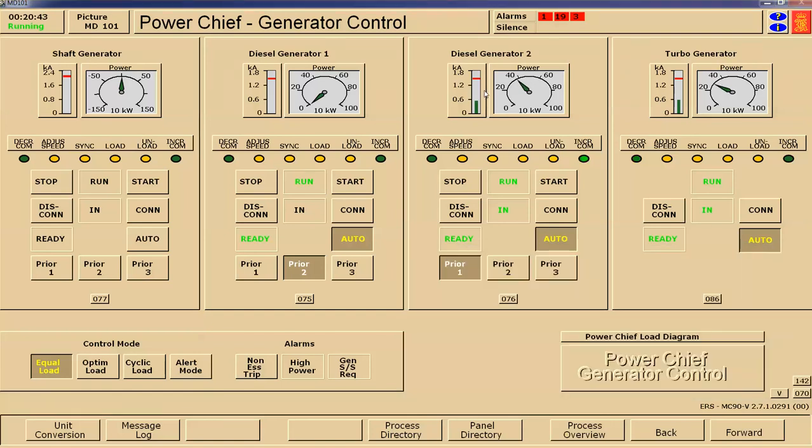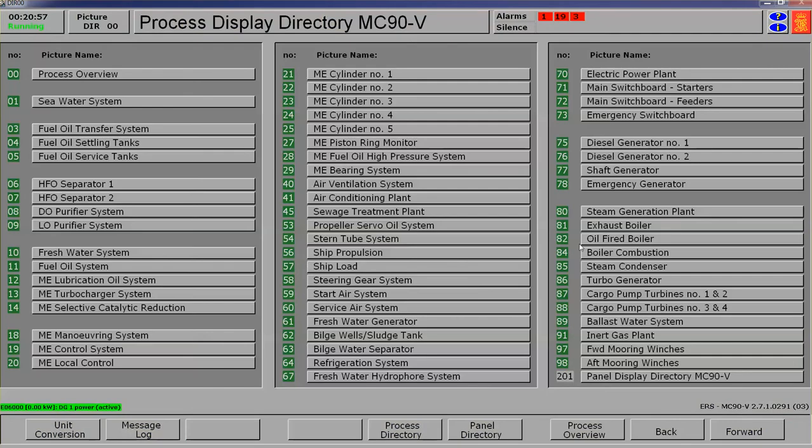All right, so that's what's supplying our power, is the steam turbine generator on the boiler burning heavy fuel oil, and the diesel generator number 2 also burning heavy, and diesel generator number 1 that was on distillate is secured. So let's accommodate the mates and do the steering gear.